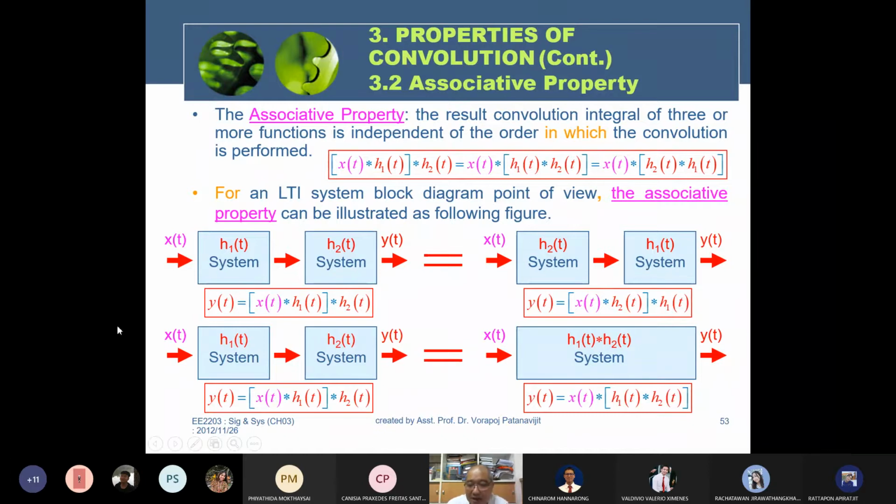Why? For example, if x is the signal from the microcontroller, S1 is the amplifier, and S2 is the motor drive. S1 makes sense, because the signal from the controller is very small in voltage, so you must amplify it in a suitable form and feed it to the motor.